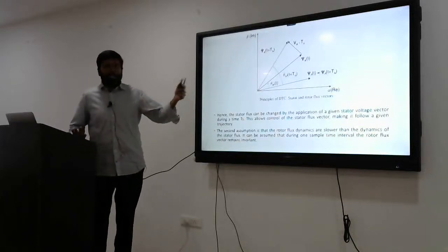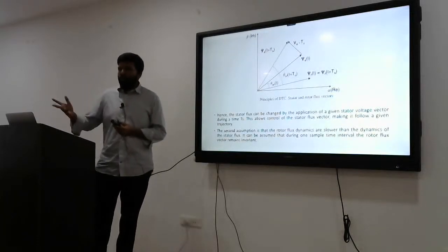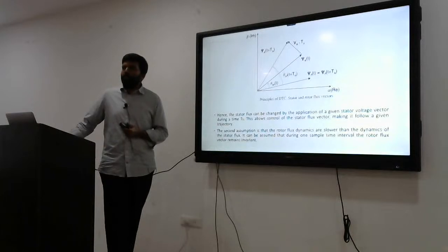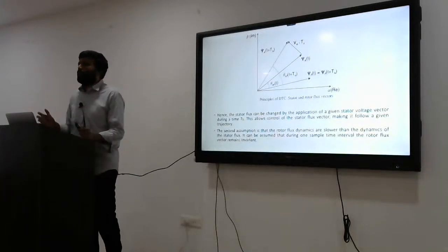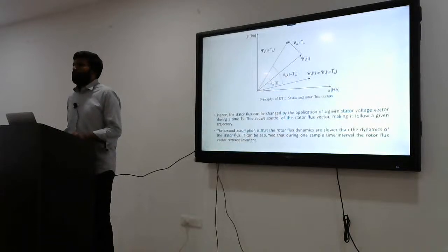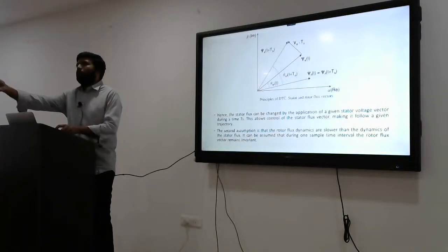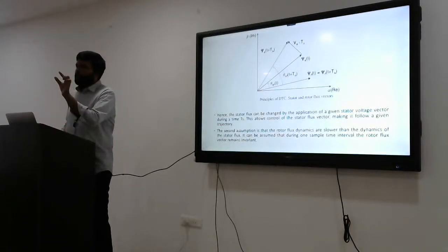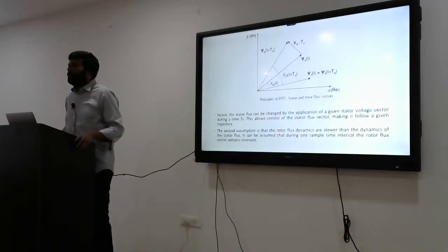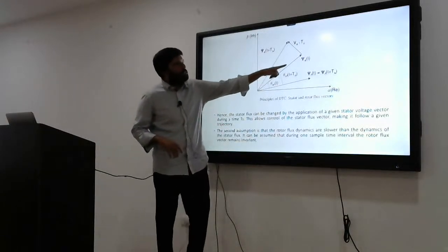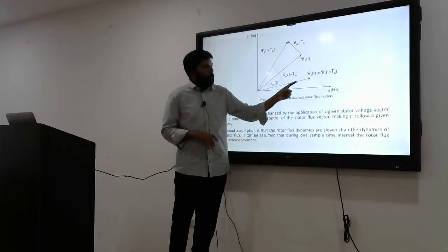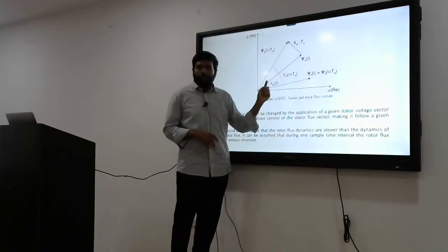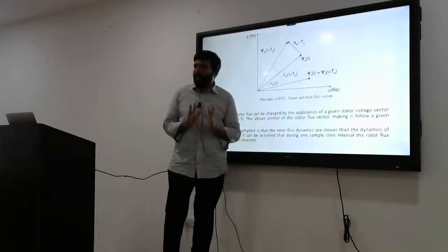This is the phasor diagram. You might have already studied it in your undergraduate course, right? This is the standard phasor diagram. In an induction motor, what is the nature of the stator flux and rotor flux? What is the mathematical expression for torque? Torque equals psi_s psi_r sine delta, which we discussed in the morning session. This is the stator flux, this is the rotor flux, and this is the space displacement angle.